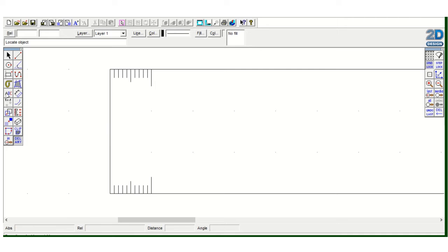Now we're going to add some measurements on there, and in order to do that I've just clicked ABC, because that's how you do your text. So ABC is selected, and as you can see I'm still jumping from dot to dot, which is not ideal now because I need the 10mm number to be off of the dot.